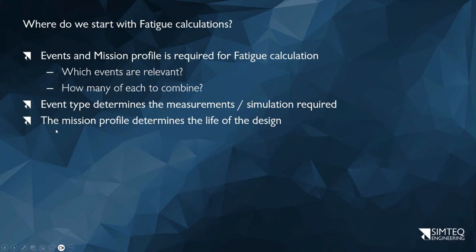Effectively, if I want to design something for a mine, a vibrating screen, I can do an operating vibration characteristics damage calculation, and I can simply do a shutdown and startup and say a shutdown and startup cycle equates to this effective total life, because you do not get to decide how many times the mine will shut down and do startups again on there.